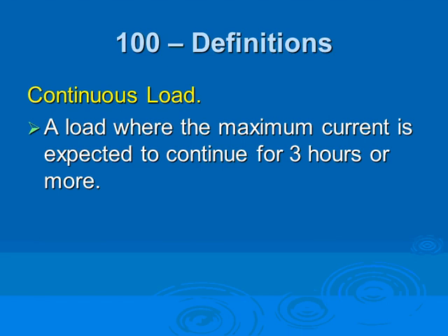The exception is for so-called 100% rated circuit breakers. 100% rated circuit breakers, as the name indicates, means if this is 100 amps, it's 100 amps, continuous or non-continuous. Typically, you start dealing with these if you have 1,000 amps or more. You can go down to 600 amps continuous duty or more, but it typically starts making sense at 1,000 amps or more, at any voltage.